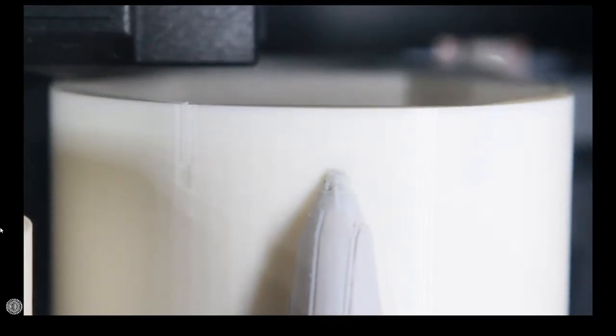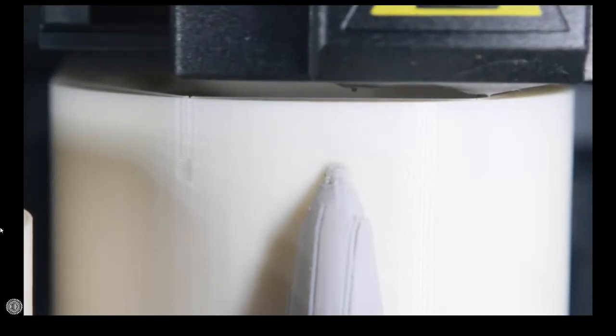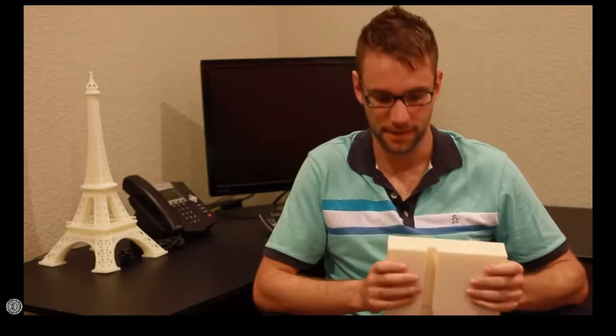The biggest disadvantage with FDM is the speed. FDM machines are slow. A decently sized part could easily take a day or longer to build. This is one of the reasons that a lot of companies don't even offer FDM. It's an absolutely phenomenal product, and it can be very cost effective. But unless you have a whole fleet of machines like we do, it's just not economical for people because if they get a couple jobs, the machine is booked for weeks. With that, one of the things that you almost always have to budget with FDM is time.